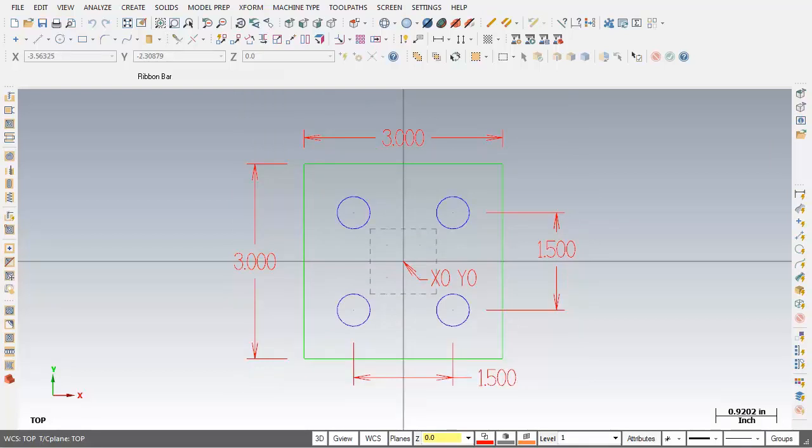Hello and welcome. In this video we'll review the coordinate system, absolute coordinates and relative coordinates. Absolute means the values are in relation to the origin, x0, y0, z0. Relative, on the other hand, is the distance from one point to the next point, an incremental distance.